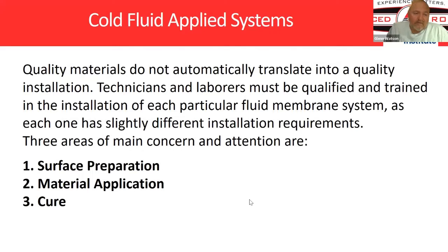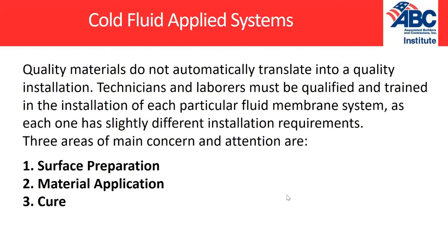Hands-on training is definitely the way to go. You're going to experience the trick, like Clay was talking about, the air bubbles in the mixture with PMMA. When you're putting down that product, you basically go back and start putting your top layer to get your 3-course in effect. As you're applying that, if you allow that roller to get dry, it starts plugging on the mat. It starts inducing air bubbles into the mix.